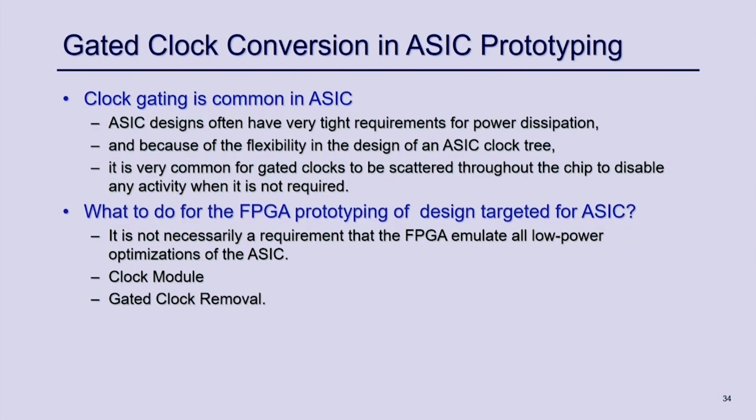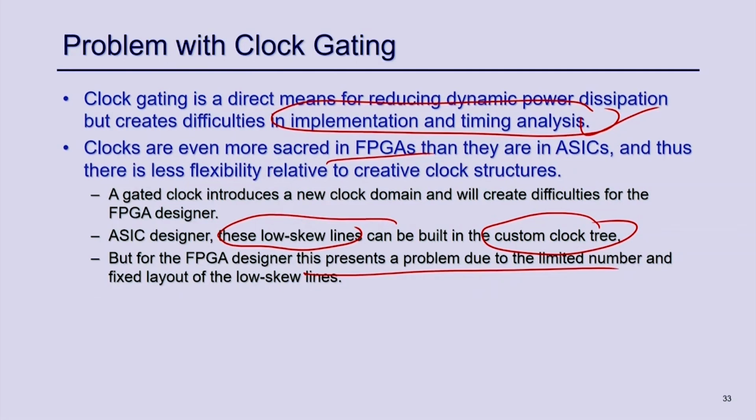But for FPGA, this is a big problem, that we cannot use clock gating at all, almost, right. And you also remember that FPGA is a very power hungry module, where power optimization does not work, because it is a redundant technology, right. It has reroutable interconnections, reprogrammable logic. So, all are kind of redundant circuits. So, FPGA in general is very power hungry. So, low power techniques for FPGA do not work. People who are actually working on FPGA do not bother much about power issues for an FPGA target.